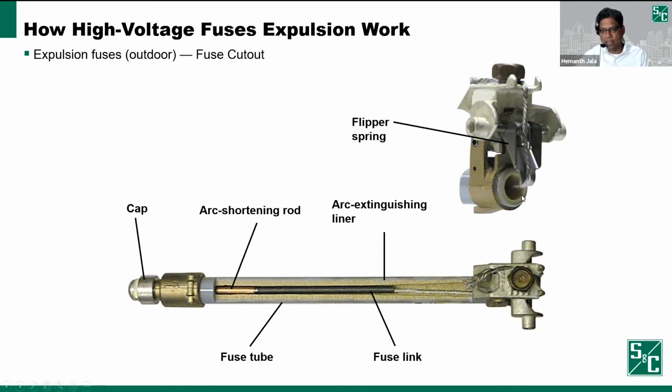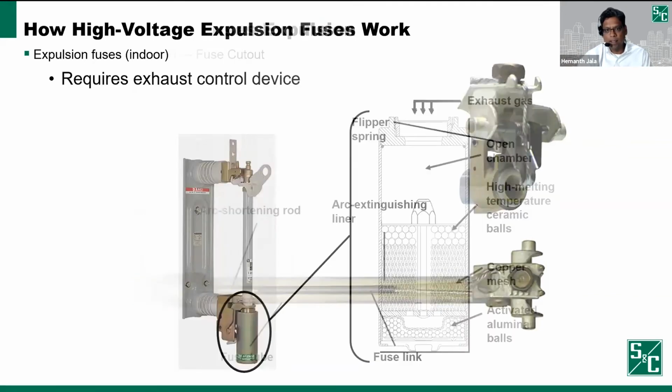It's actually pulling it, and you have a tension on the element, and when the element melts, it goes through the process we just talked about. So once this operates, the fuse tube drops open, and that's your visible indication that that particular phase has a fault. You need to go check the fault, clear the fault, come back, either put back the new fuse unit or replace a new fuse link and close it back in, and you're back in business.